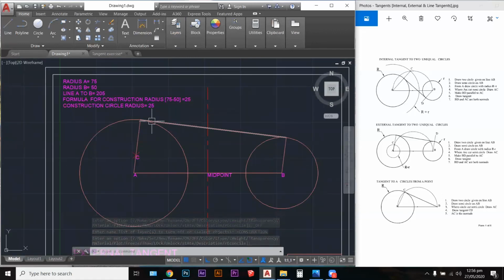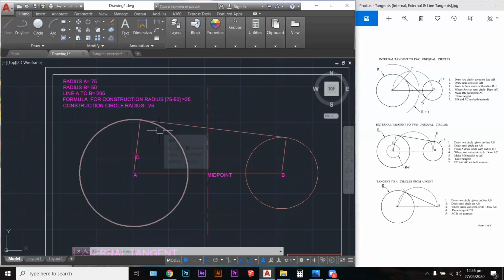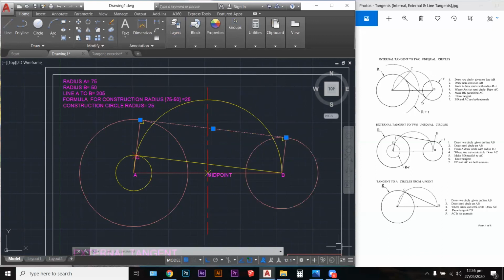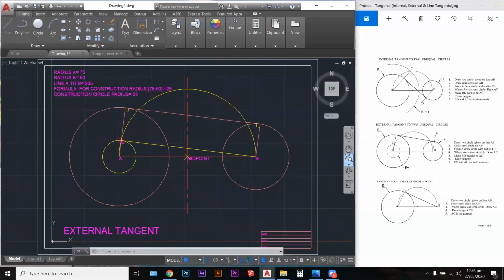So you can see how two unequal circles are firstly joined together by a tangent line. And this can be proven because at the point of tangent, if you pull a line from there right to the axis of the circle, the angle is 90 degrees. From the tangent line to the axis of the circle, that is a 90-degree angle on both circles. So I'm just going to turn back on my construction there now. And let me just put this into the proper frame.